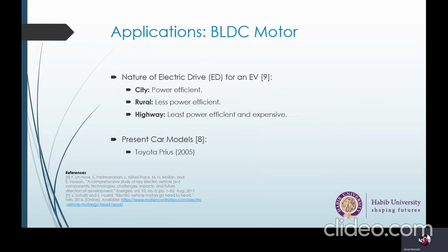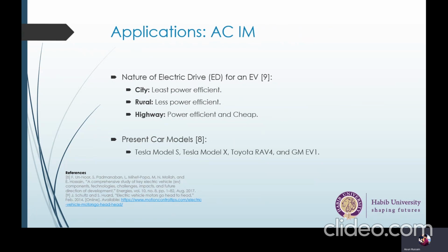A study based on finite element analysis was carried out for both the brushless DC and induction motors, and it was found that the brushless DC motors perform better in city scenarios where there were more frequent starts and stops, more frequent high torque and acceleration was required, and the speed was slower, as compared to a highway where the AC induction motors perform better, where high speed and high constant power was required and there were less frequent starts and stops.